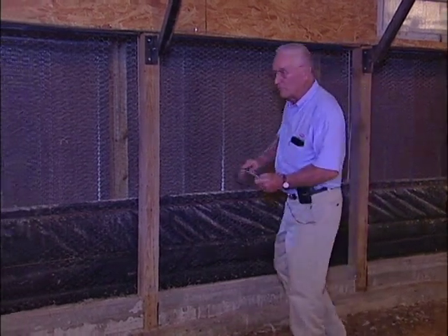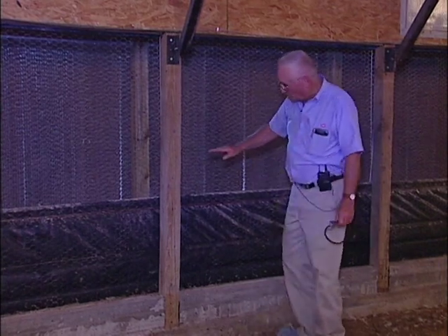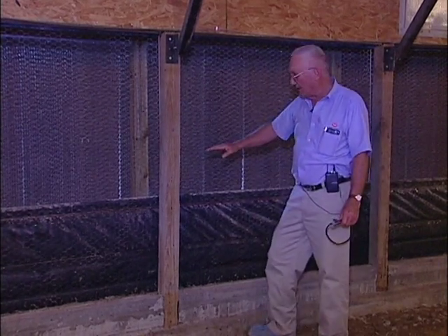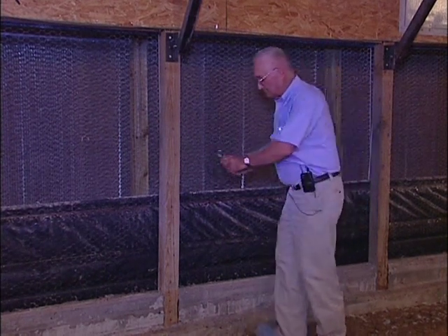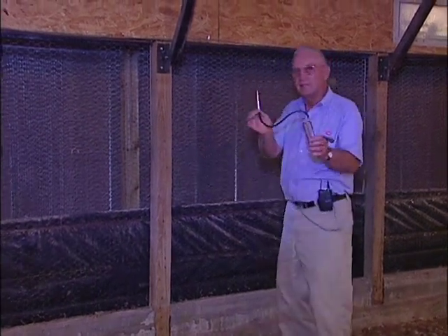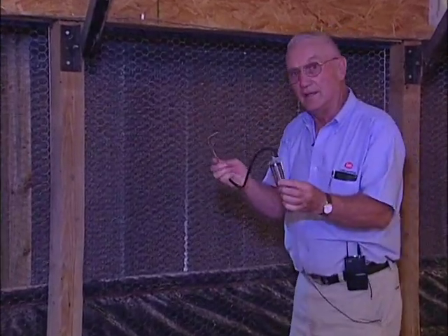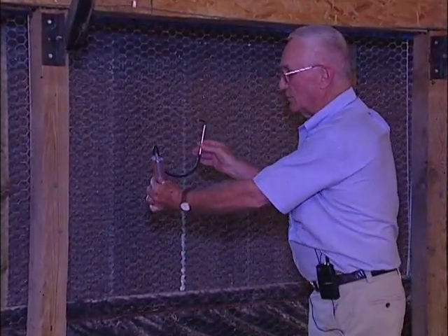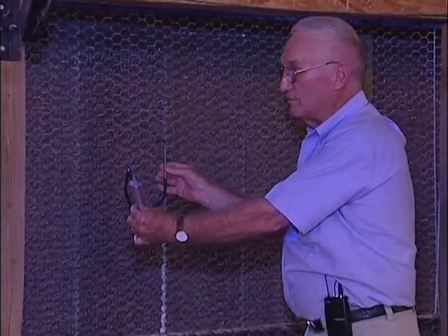So when we measure our pressure drop coming into this house, we want to measure our pressure where the air enters, just about 10 inches to a foot above the curtain. Now, on this instrument, if you let the air cross this port and this port at the same time, then the instrument's not accurate. So we don't hold the instrument as such and try to measure the pressure.